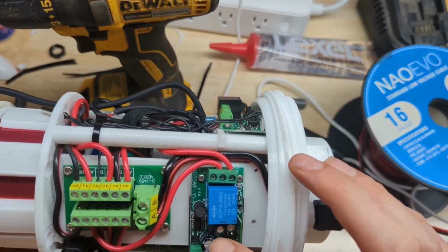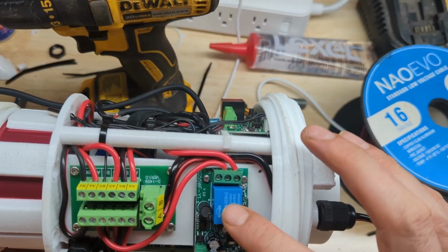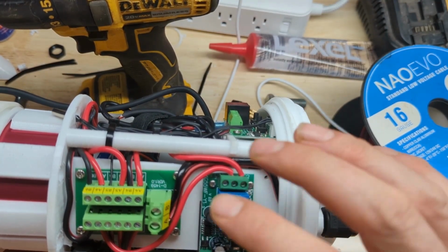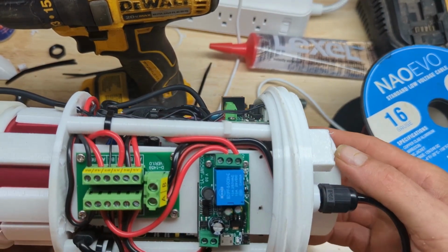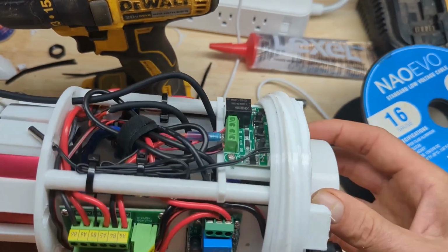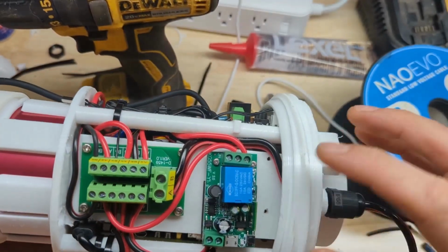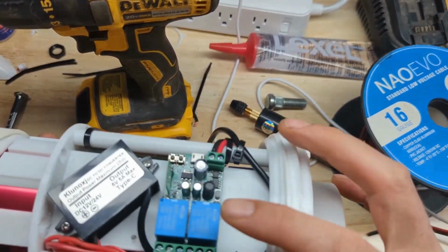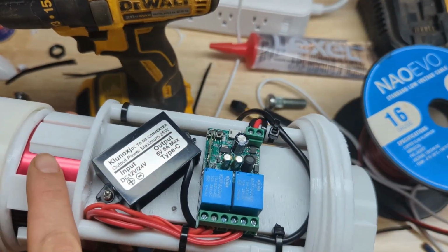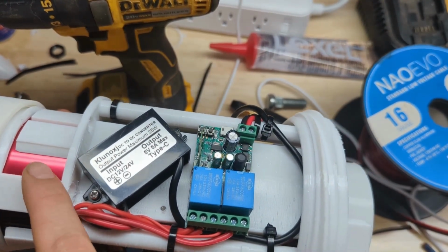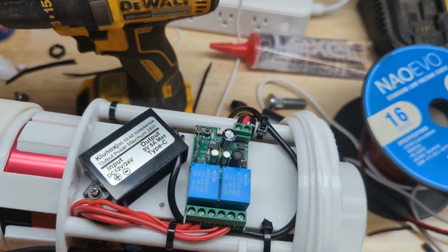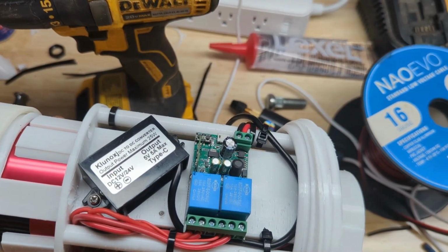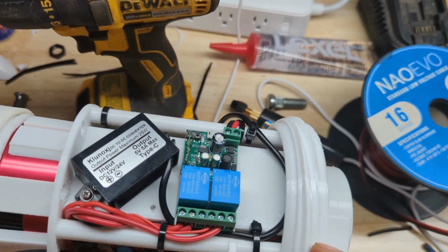I think the capacitor does not hold enough charge, so when it's actually firing up a component, like one of the switches, the dew heater, when it starts, it's generating heat, so that's obviously going to pull a little bit more power than, say, the camera would on its startup. Whenever it first clicked on, it was causing the camera power to fade out, and that would cause the camera to drop briefly, just long enough that the Raspberry Pi thought it was offline. The only thing that corrected that was rebooting the Raspberry Pi. And of course, if everything else was already on, no other issues.